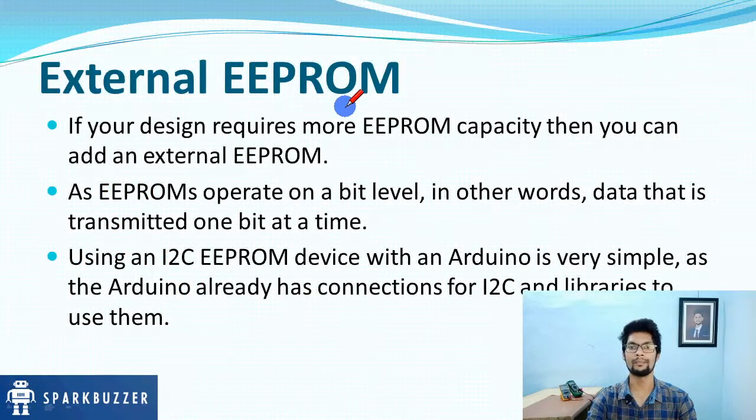External EEPROM. If your design requires more EEPROM capacity, then you need to add an external EEPROM. EEPROM operates at a bit level, 1 bit at a time. Using an I2C EEPROM device with an Arduino is very simple, since Arduino has a connection for I2C and libraries to use them.